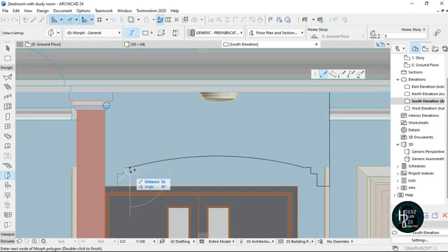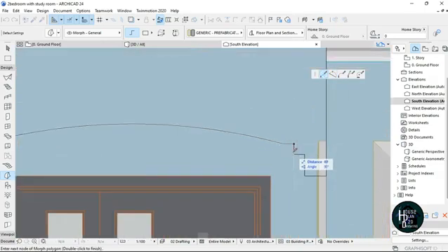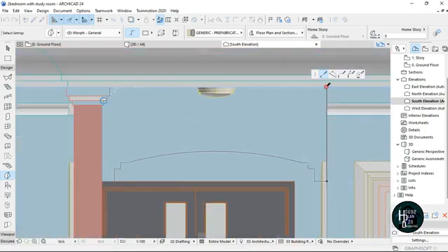And once you reach this point, select on this arc by 3 points. Select on it. Select this other point here. Then drag it up. Then select on this straight segment and continue tracing out your line. As you can see, it turns white.